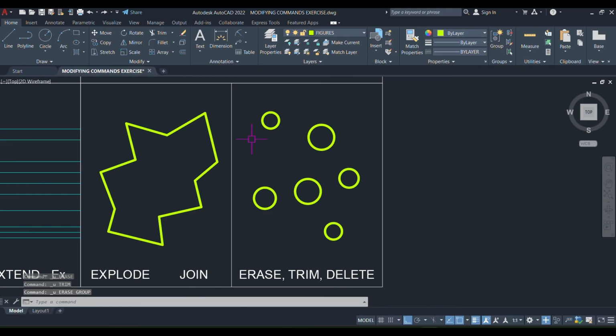Now, let me discuss a little bit on how to use your different selection tools. So click anywhere on your screen. Now you'll notice that the square is green, right? Whatever it touches will be selected. Now, if you use the selection tool going to the right, that would give you a blue square. Now, what does this do? Whatever is inside the blue square would be selected.